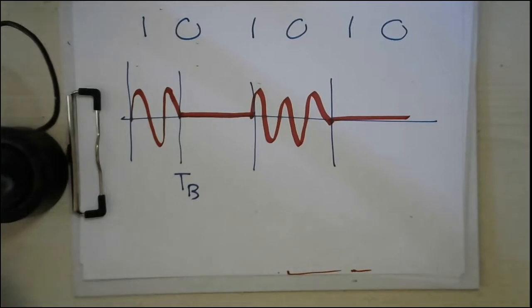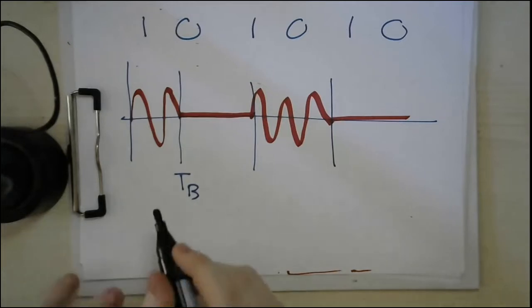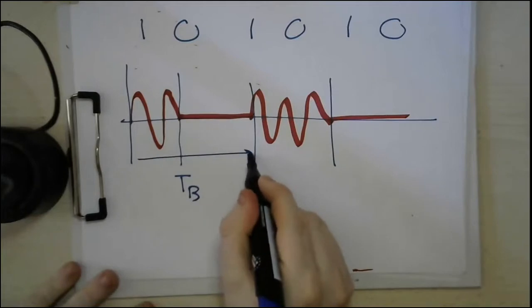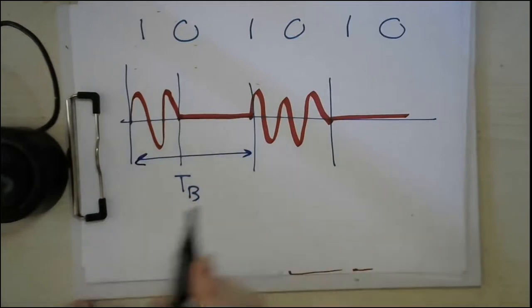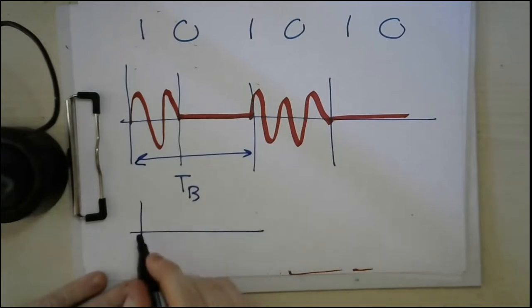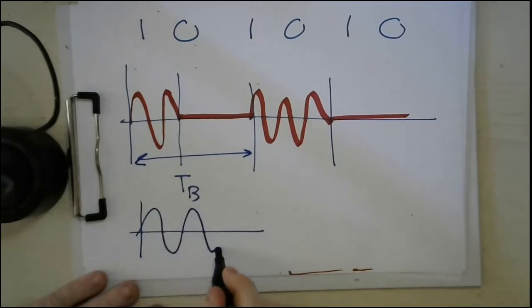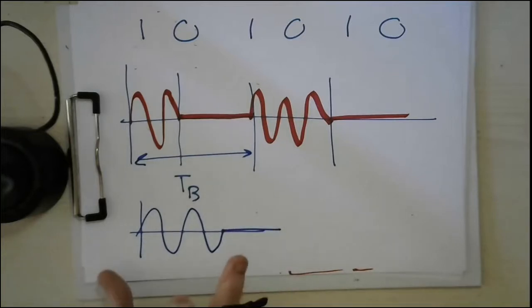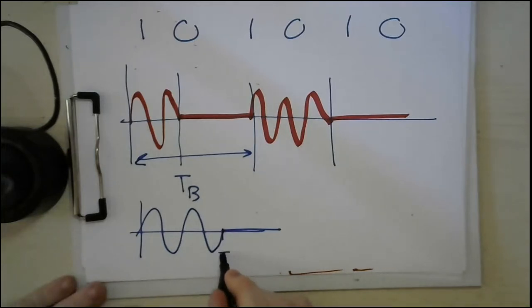So if you have a periodic signal like that, and you would like to calculate the Fourier transform, then your first step is to consider only one period. So, okay, this is one period, for example. And then start to write an equation to describe this period.